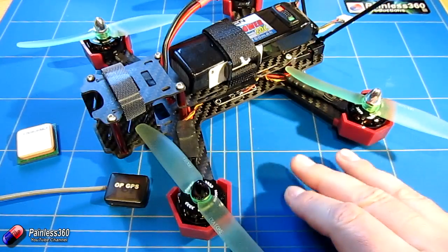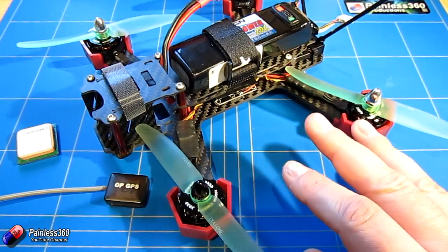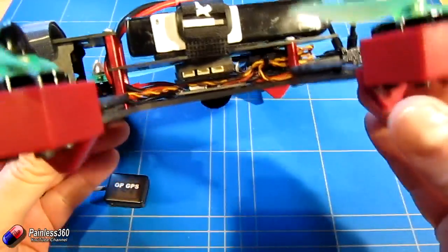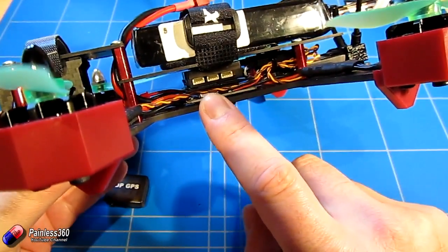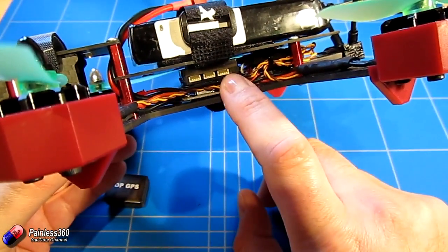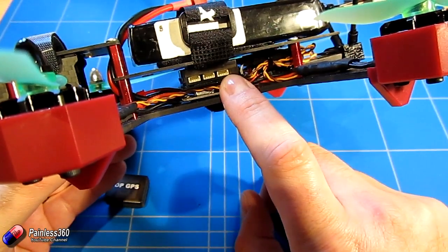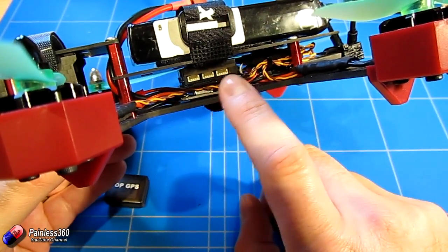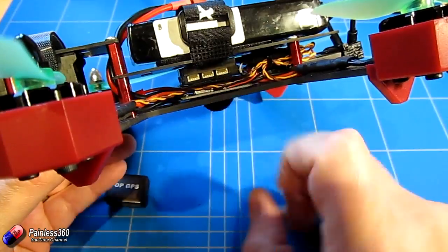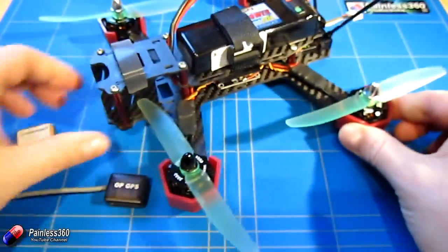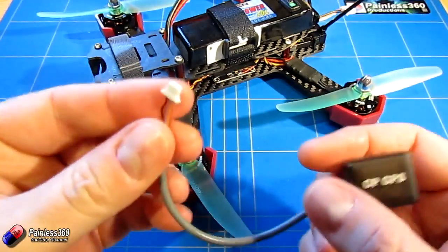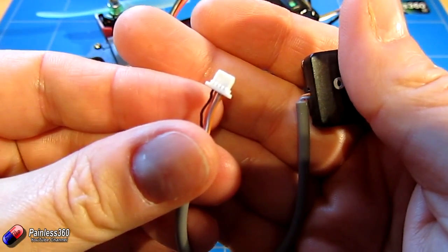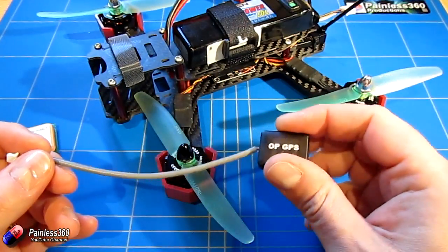So first of all, let's talk about how you actually connect the GPS to the CC3D. On the side of the CC3D Revolution, which we have here, we have 3 ports. This one at the very back is the main port, then we have the auxiliary port, and then we have kind of a sensing port. The main and auxiliary ports, the one at this side and the middle one, can be used to plug the GPS into. The GPS that comes in the kit is all set up, and the 4 wires at the end are: the black is ground, red is +5 volts, and the other 2 are send and receive.